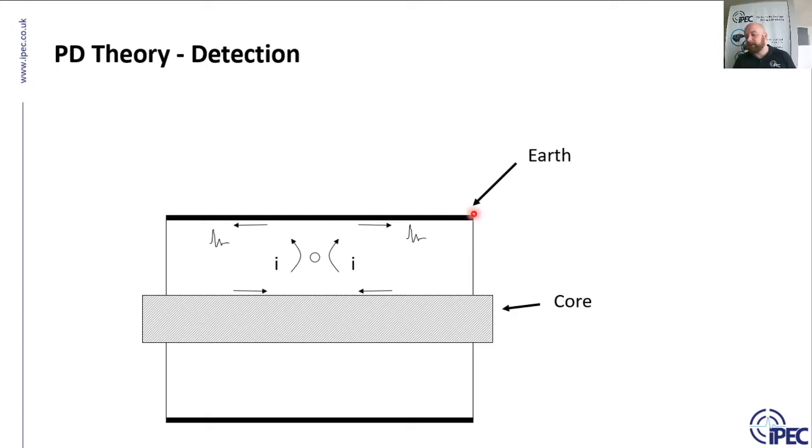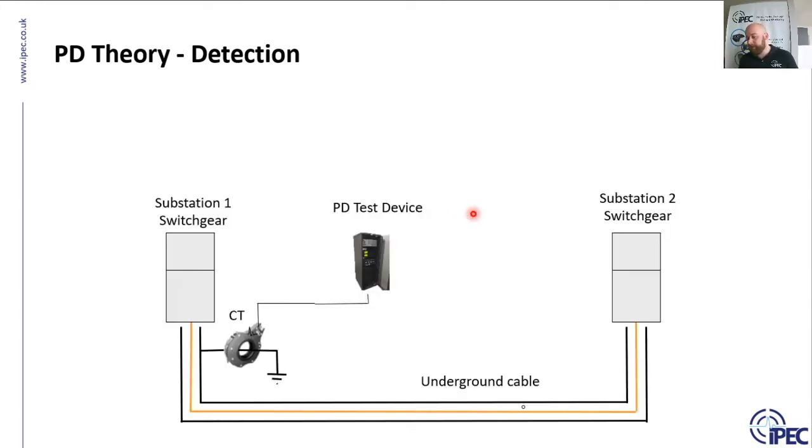So this high frequency signal is traveling along the inside of the cable. If my animation works this time, it will travel, there we go, along the inside of the cable earth in our example, come out at the switchgear and through the HFCT.